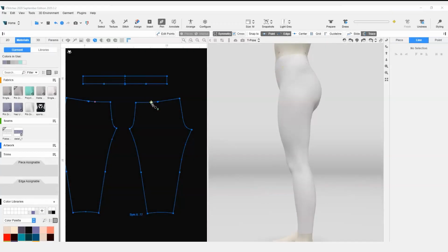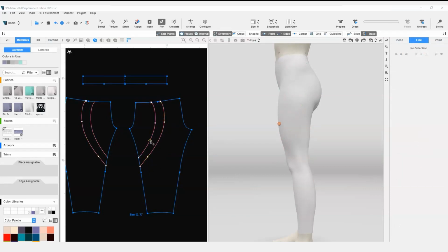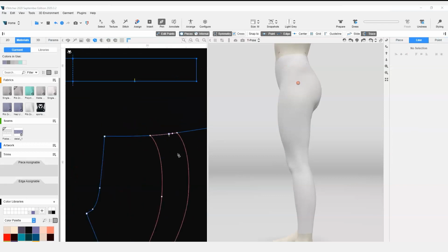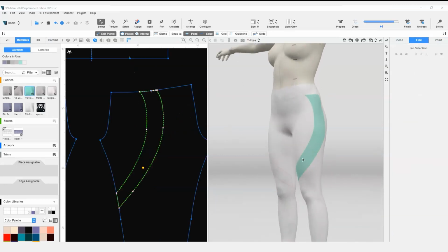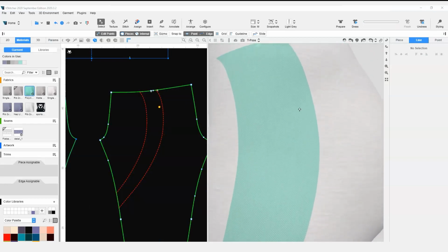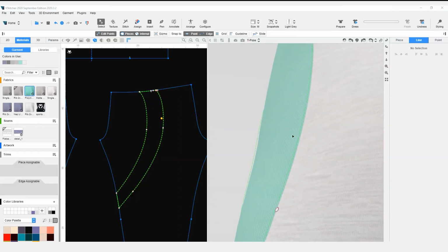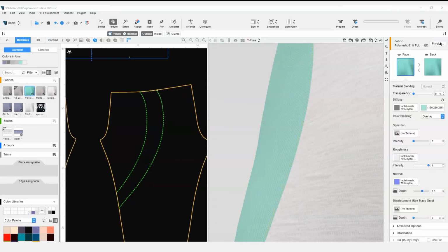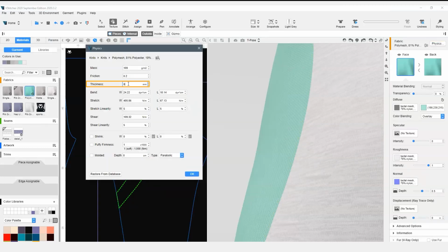When creating a closed cut mark, we can also join lines. For example, we create this line and make a copy of it and trace the outlines. We then choose both points. Go to the context view and click Join. These two parts appear to be on equal planes. That's because both fabrics have the physical property thickness set to 0. Using this option creates a smooth look that fits the seamless design. If we want one of the pieces to pop out a little, we can change the thickness value to create the style effect we want.